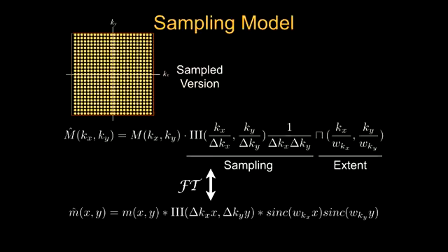Here, the sinc is basically giving a blurring. If the main lobe of the sinc is very wide, you're convolving with the sinc function, so your actual signal will be blurred. So a tighter sinc is important, and the sinc governs your resolution. If the sinc is very thick and it's convolved with some object, then everything will be blurred.